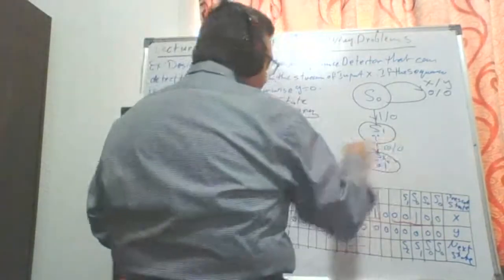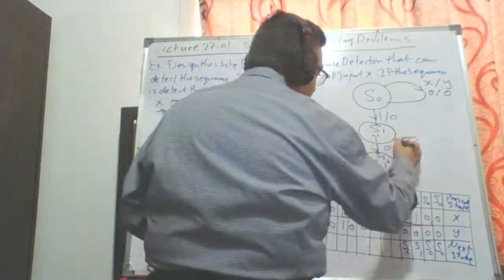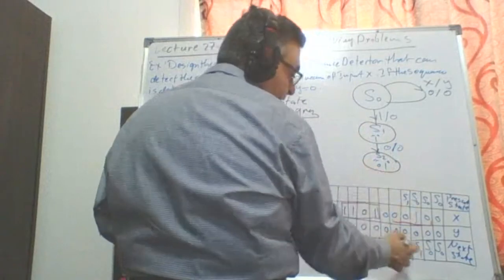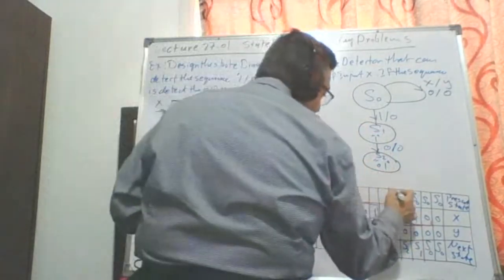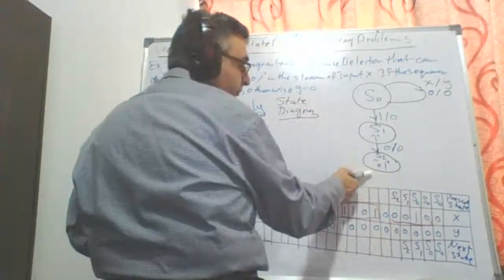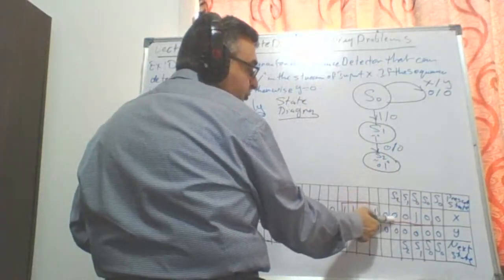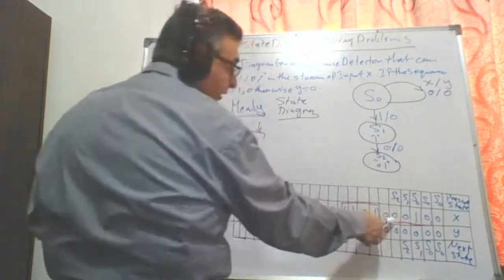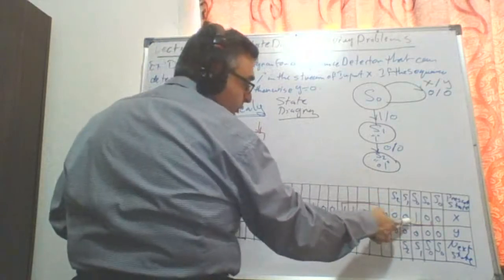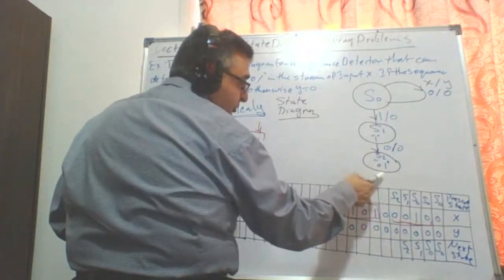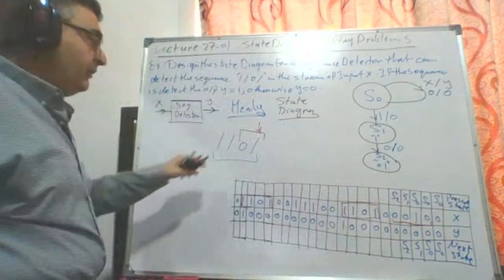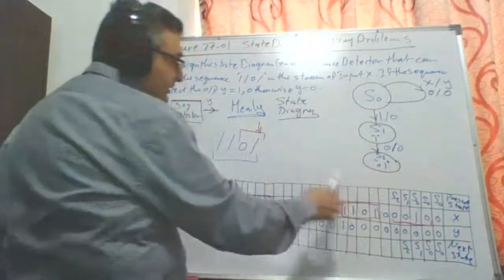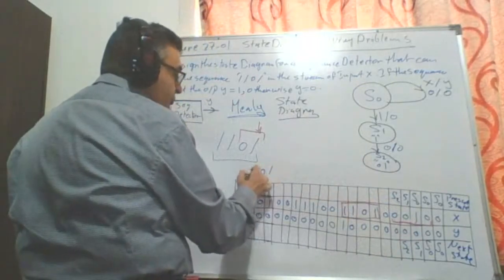So if I have x equals 0, I will go to state S2 and I remember that. So now I am in S2. What do I receive at S2? I'm receiving a second 0. So my history has 1, 0. If I'm now in S2 and I received 0, that means the sequence that I have right now is 1, 0, 0.